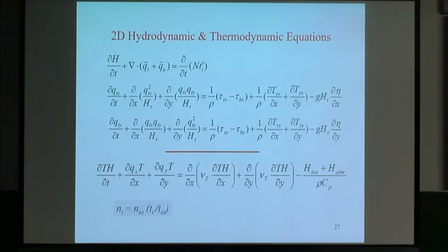At that time, I just said, this is how I feel. But why is that? Okay. Recently, we looked into this, and we can show that the reason the roughness or flow resistance increases with the thickness of the jam or accumulation is mainly the head loss due to the seepage flow in the jam. And actually, you can calculate that.